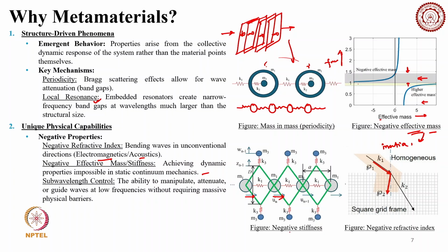And here also, once you have that negative stiffness and you are exciting the structure, you find that once the structure goes to resonance, the whole thing moves in the opposite direction. It is something like you are pushing the structure, but in return, instead of having some thrust on you, it is the opposite way. So your stiffness becomes negative with the frequency.